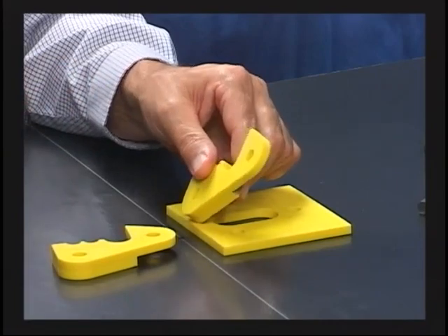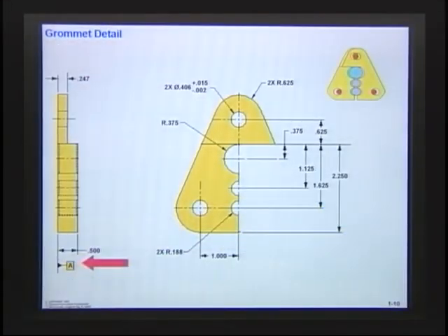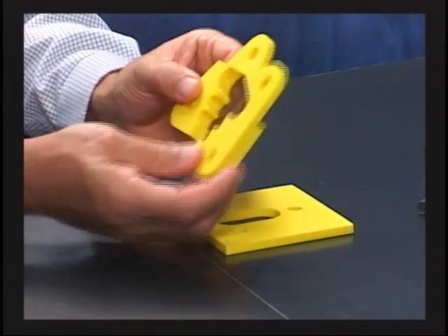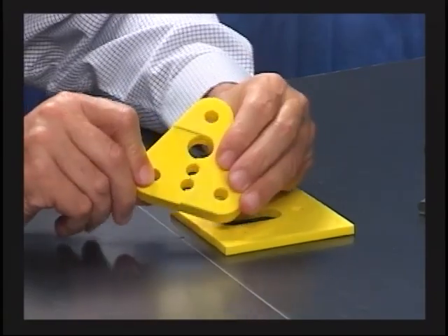All right, now let's take a look back at the graphic. Number 2, what did I select as my secondary datum? I call that surface off as datum B, and I call that surface off as datum C. Now, why did I do that? Well, this is what I thought. When the parts were coming together, you see how they're coming together? I take these two parts and I put them together.